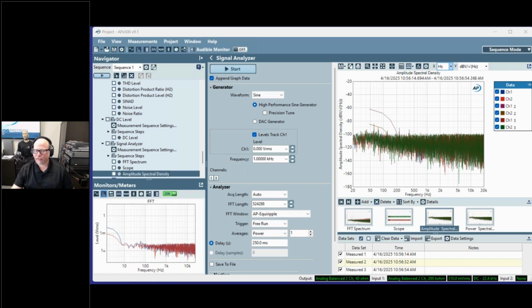And yes, if your power amplifier has digital inputs, S/PDIF or PDM or I2S, whatever, the measurements are really the same. The only difference would be in signal path setup, you would pick the appropriate output connector.